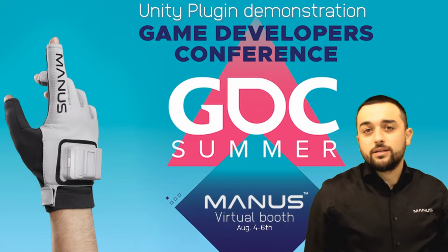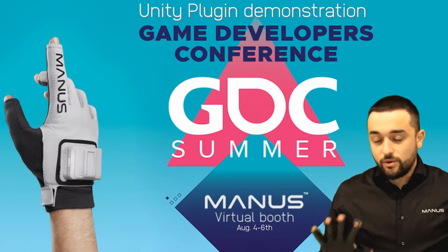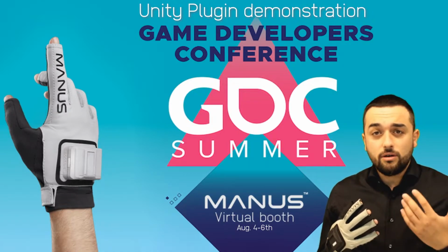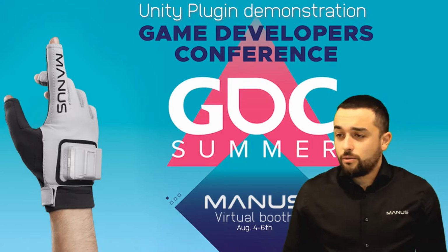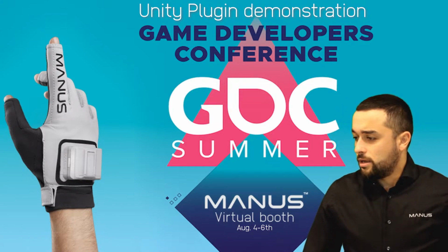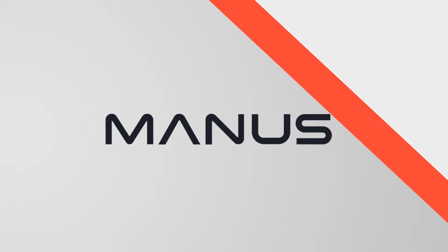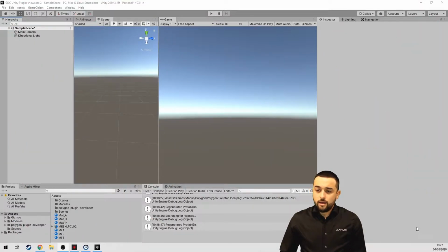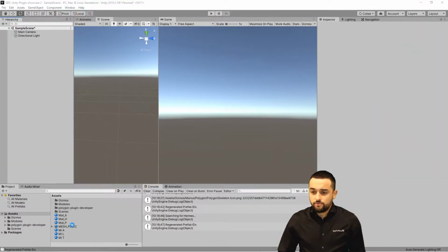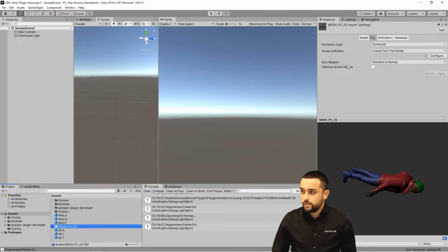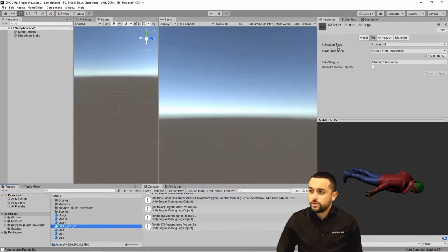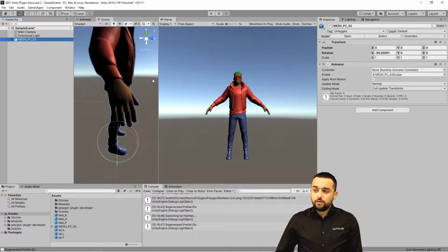So what I'm going to start with is show you how easy it is to implement our gloves on your custom 3D model. I'm going to open a Unity project, and I have a free to download 3D model that I got. First thing I need to do is make sure that it's rigged and that the animation type is set to humanoid. Afterwards I can just simply put it inside of my project.